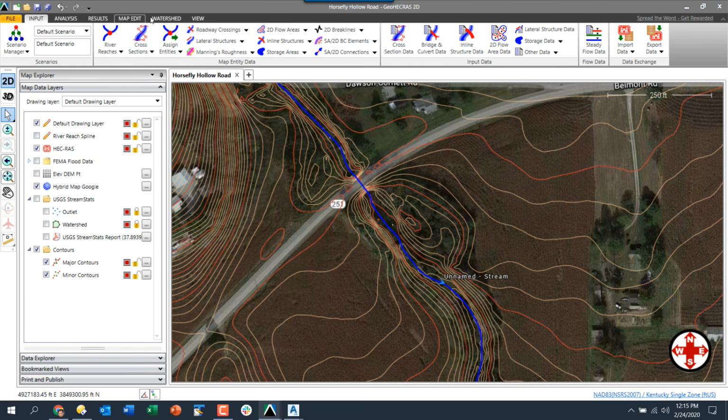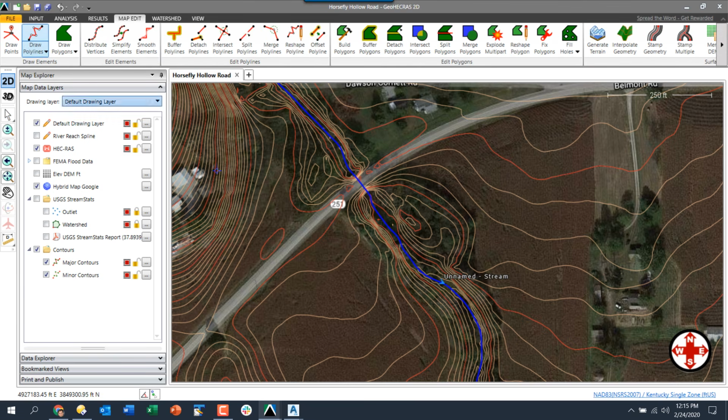So one way I could do it, just to show you, is I could come in, and I'm just demonstrating. If you guys watch my screen, I could just draw in a polyline representing where my section might go. So I want to cut it perpendicular to the contours. I want to capture, I guess, kind of in here. Well, it's kind of hard to get perpendicular. It's kind of hard to see what's going on. But I might do something like that and then say, no, I don't like it over here. This isn't very good. So I could grab this line, press function key F4 again, and I can grab that vertex. So I can manipulate these lines ahead of time so I can get this exactly where I want. So you can come in here and adjust this.